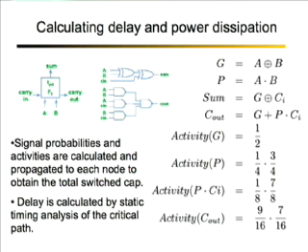Finally, we are looking at some of the bigger circuits, and the biggest circuit that we have is a full adder. It's an 8-bit ripple carry adder that we have simulated. So a user can provide the IV and CV characteristics of an NMOS and a PMOS and get switching energy, switching power, leakage power, and delay of the critical path of an 8-bit ripple carry adder.